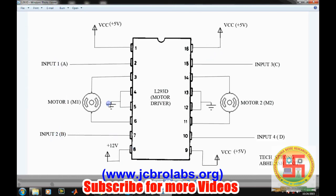These input pins, that means pin number 2 and 7, need to be connected to the microcontroller, from where we are passing the command, and pin number 3 and pin number 6 should be connected to the motor. Similarly, for the second port, pin number 15 and 10 should be connected to the microcontroller, 14 and 11 should be connected to the motor, while 13 and 12 go to ground. So logic 1 or 0 can be used to turn this motor on or off.